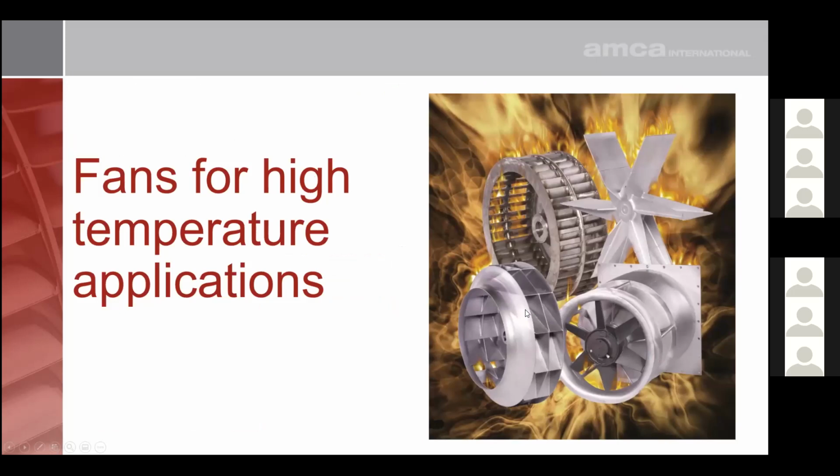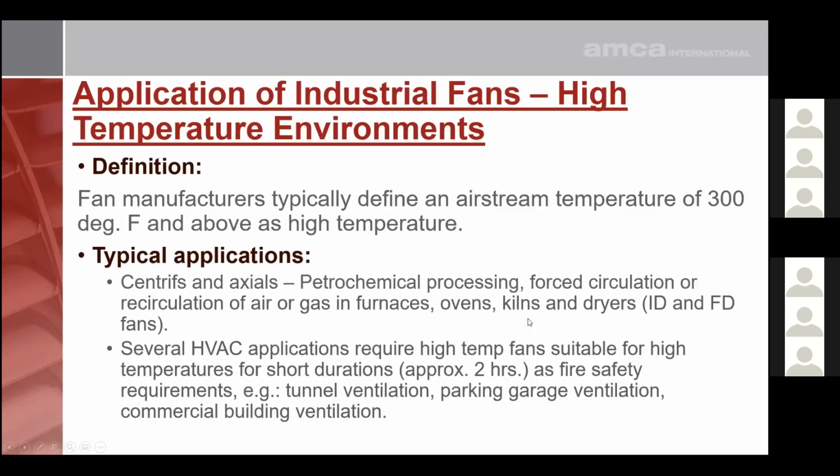So moving on to fans for high temperature applications. In the fan industry, we define a high temperature environment as one where the airstream temperature is 300 degrees Fahrenheit or higher. We typically come across these applications in petrochemical processing, forced draft circulation, etc. I'll point out that in HVAC applications, we typically see high temperature requirements too, but that is for specific durations of less than 2 hours, which is mainly for fire safety. Basically those fans should work in case of a fire and last through 2 hours of the fire.